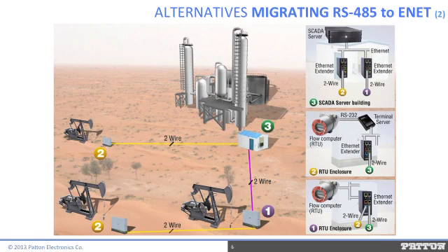Install a pair of Ethernet extenders over a single twisted pair infrastructure. Instead of deploying individual point-to-point links to each derrick's flow computer, use MDE Ethernet extenders in the daisy chain fashion to reach the most distant derrick while accessing intermediate derricks with the dropped Ethernet connection from each MDE device.